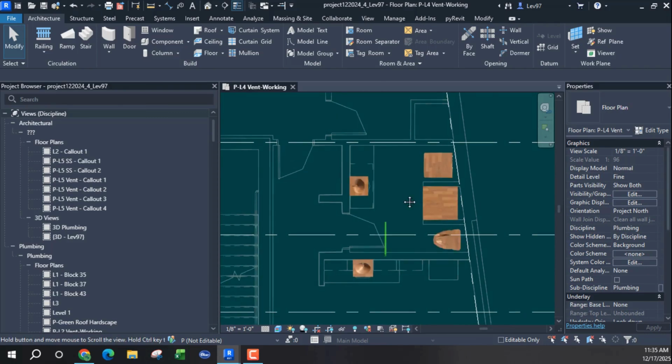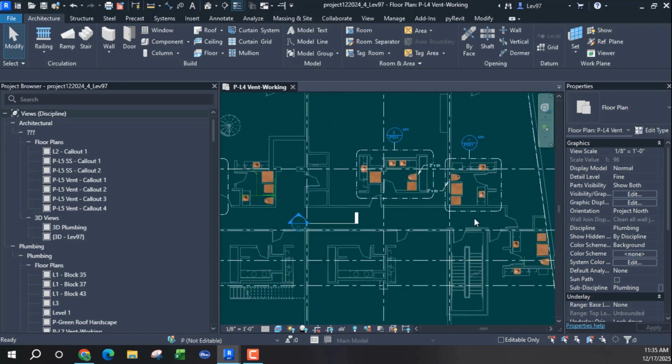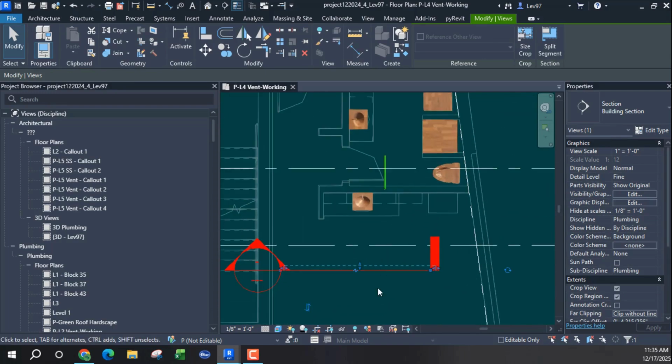And now we're going to come to another part of the plan where I want to point out how to lay out. Now this is how I lay out my vent system, just like you lay out your slab and your penetrations for your sanitary. So you have to lay out how they're going to penetrate if it's going down through the walls, let's say from the first floor down to the basement or the sub-basement, depending on the slab. So you have to create stub-outs, okay? So we're going to create some vent stub-outs.